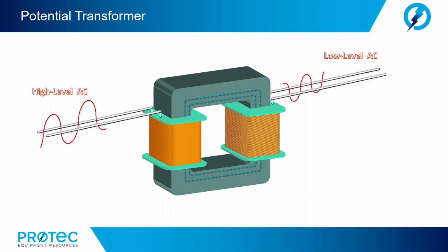The working of PTs is like any conventional transformer. The electrical energy is transferred between the primary and secondary winding through magnetic induction. The alternating voltage at the primary generates alternating magnetic flux in the transformer core. Since both windings use the same core, this alternating flux induces a voltage in the secondary winding. Thus, current starts to flow in the secondary winding. Since the primary has a greater number of turns compared to fewer secondary turns, the voltage induced in the secondary is very low. The secondary voltage is measured by using a standard voltmeter.